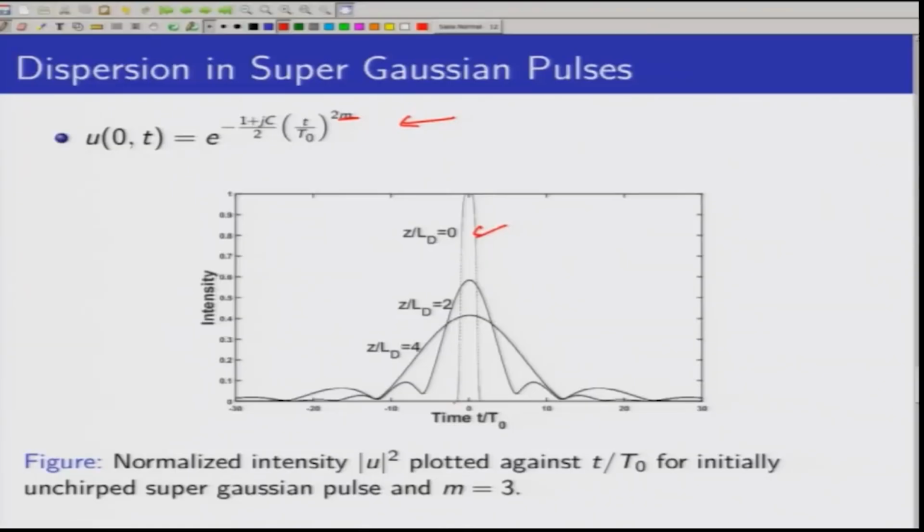As you can see, it is much steeper than the secant or the Gaussian pulses that we saw before, and the instantaneous frequencies get really high, because there is an instantaneous jump at the edges. So, there is much more distortion here. As the pulse propagates into the fiber, the trailing edges and the leading edges start distorting, and the pulse starts losing its shape. In a communication system, this would be very problematic for us. So, it is really important for us to study these effects and to probably find techniques to mitigate them.